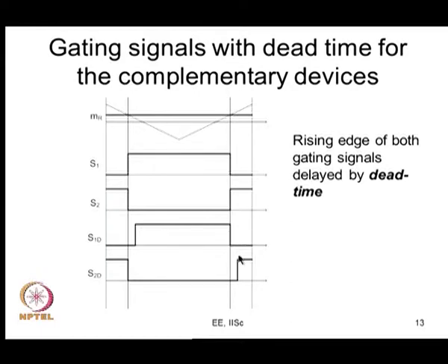For example, if there is a ripple, now let us say this is one carrier cycle time. Let us say one carrier cycle is 200 microseconds, or this is 5 kilohertz. You also have 10 kilohertz harmonics, you may also have a small amount of 15 kilohertz harmonics. So, if your fundamental current is going through 0, then it is the ripple current that matters. It is possible that you may have a ripple current like this. You get my point?